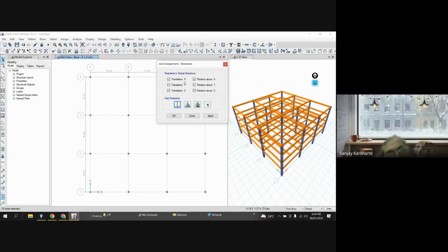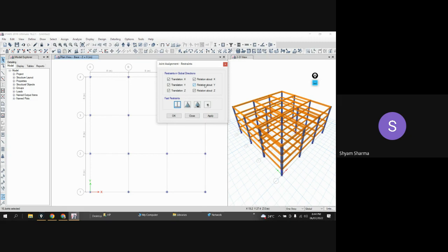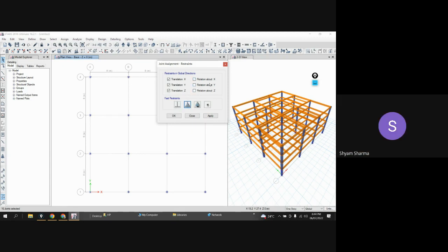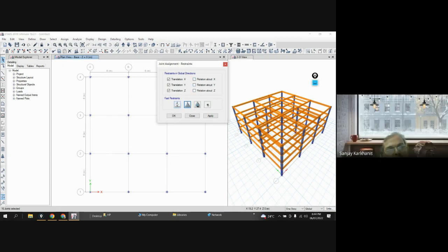तो अभी आपको क्या चाहिए? अब ये सवाल अभी ये restraint चाहिए सर हमें, क्यों? क्योंकि सर ये नहीं फिक्स सपोर्ट है वो। Okay, so you are considering it fixed. That means you are not allowing the footing to rotate about x-axis, rotate about y-axis, as well as rotate about z-axis. As well as the footing is not allowed to move in x direction, move in y direction, as well as move in z direction. That is a fixed condition.